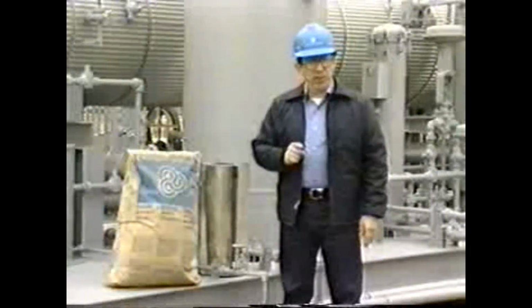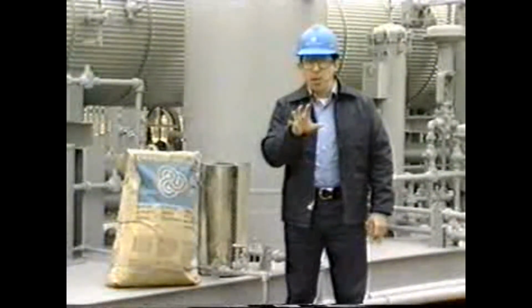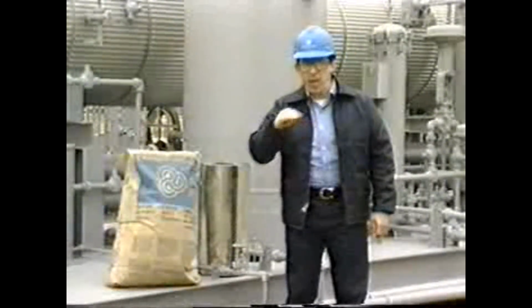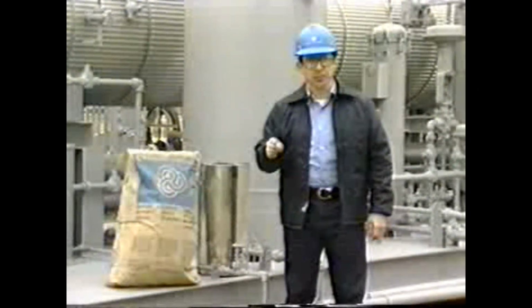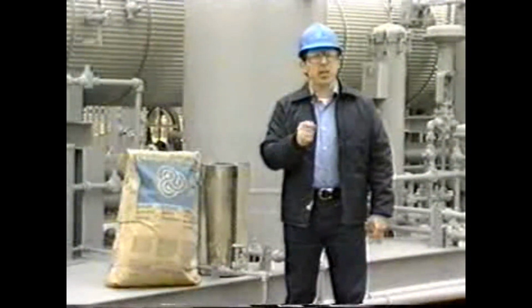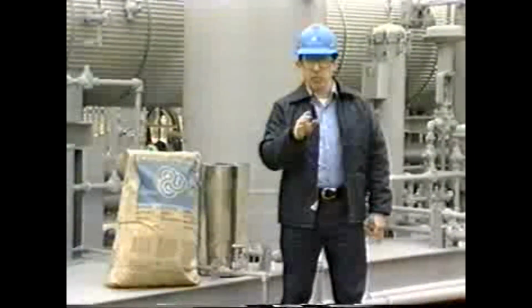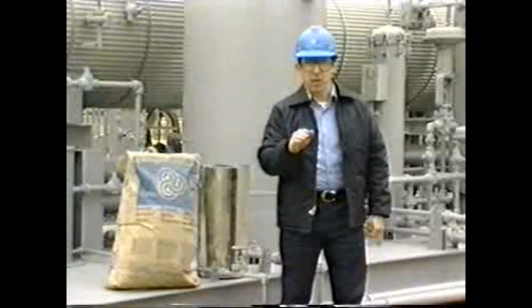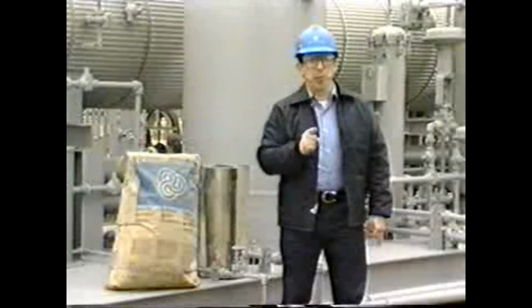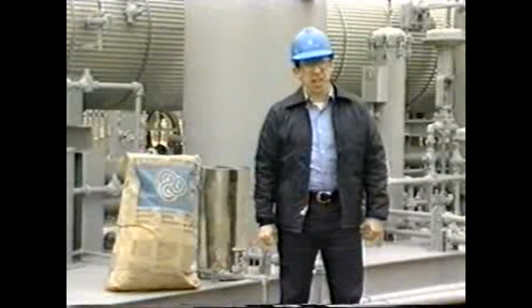When the loose fill vessel is used, carbon particles, sometimes called fines, must be trapped to keep them from entering the glycol dehydration unit. This is especially important when a fresh carbon bed is put into service. Anytime the level of contaminants in the glycol increases, the carbon filter should be replaced. Monthly tests should be run to determine contamination level.